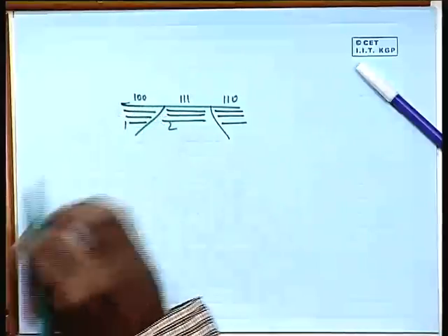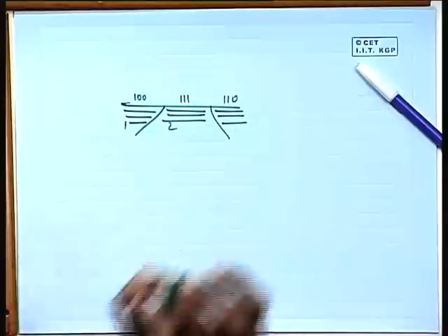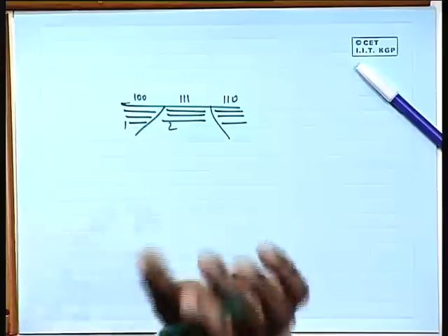If that is the case, now if you put an etchant on this uniformly, the amount of attack is going to be different in different regions, because each region will have a different energy, and that energy depends on the surface energy of that particular region, and that surface energy is different for different planes. For the 111 plane, the surface energy will be different. For 110 it will be different. For 100 it will be different for a given crystal. Let us say it is an FCC crystal like aluminum.